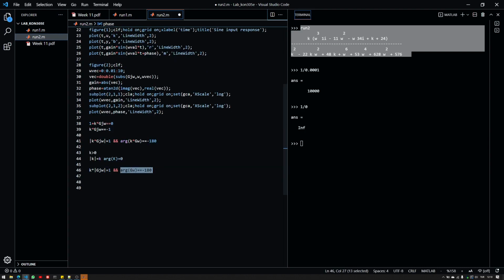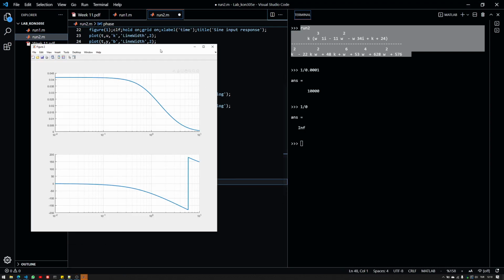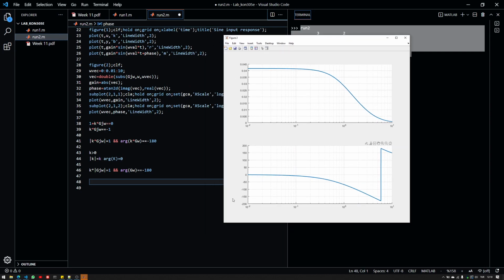And therefore, if I use the Bode graph or Bode plot, I will look for the second graph here, and I will check this point. So I will look for -180 degrees, which is somewhere here. And of course, you can see that it jumps here. So it's also not really that relevant for us, because past that point, we are not really interested in it. So yeah. At this point, I will look for the frequency, because at the same exact frequency, I should look